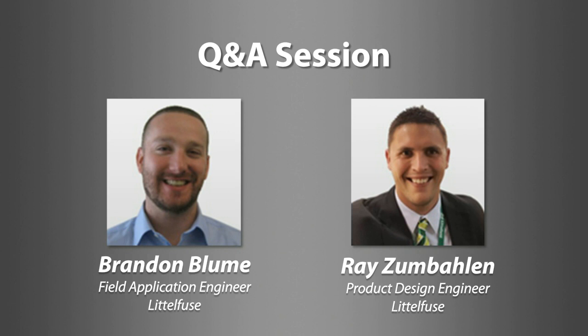That's a good question. So I guess having a current zero would be for AC applications. Obviously, DC applications do not have a current zero. So to answer the question, a fuse does not require a current zero. However, if it is an AC rated only product, then yes, it would. If it's a DC rated product, then no. Generally speaking, though, a fuse does not require that.